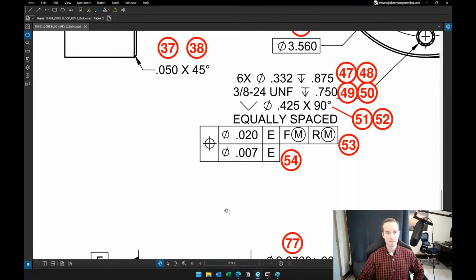So like I said, in this example, there could potentially be another tolerance below that says maybe 0.003 with no datums. And the way that we would interpret that is this one is controlling the spacing of the pattern and perpendicularity to the plane. And then the one without a datum is controlling just the spacing of the features to themselves without regard to the plane. So it could possibly best fit and twist.